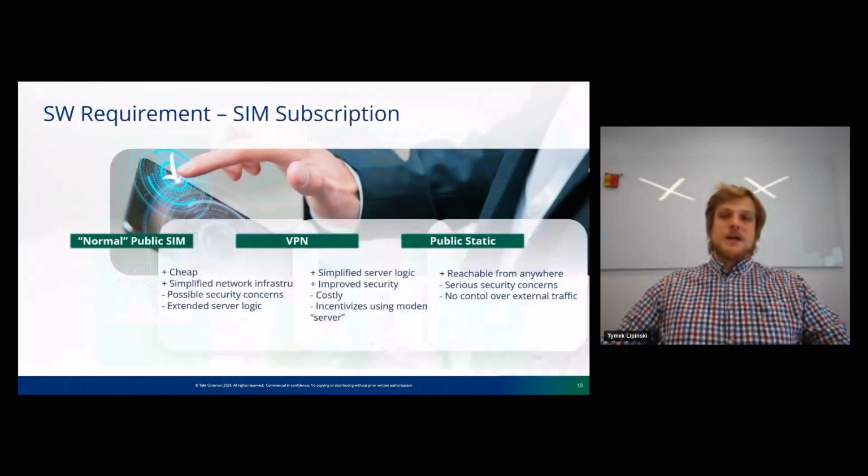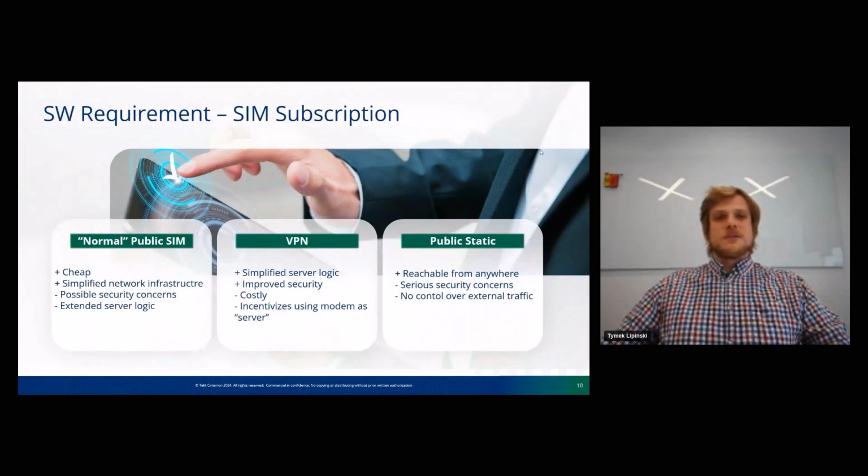Then later we decide on our SIM subscription, what kind of SIM we will be using. So we can use a normal public SIM, maybe VPN, or a public static IP SIM card. Well, the normal public SIM card, it's cheap, it has simplified network infrastructure, but it has some possible security concerns and it requires extended server logic.